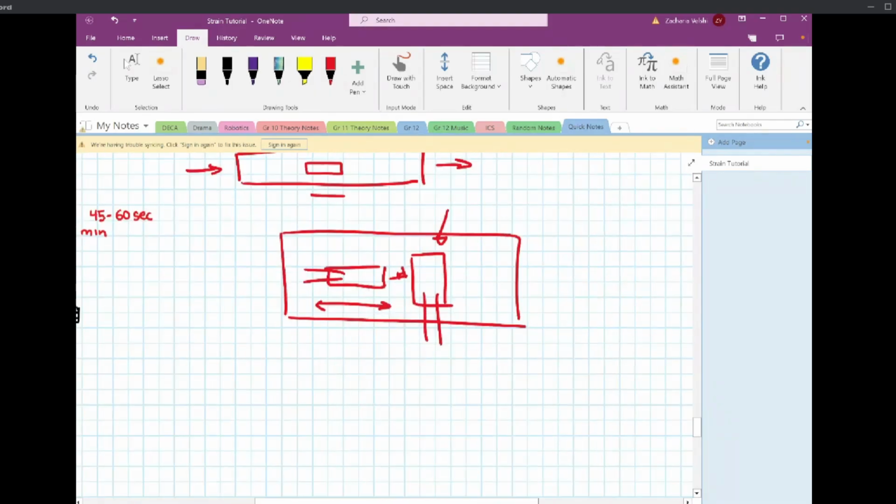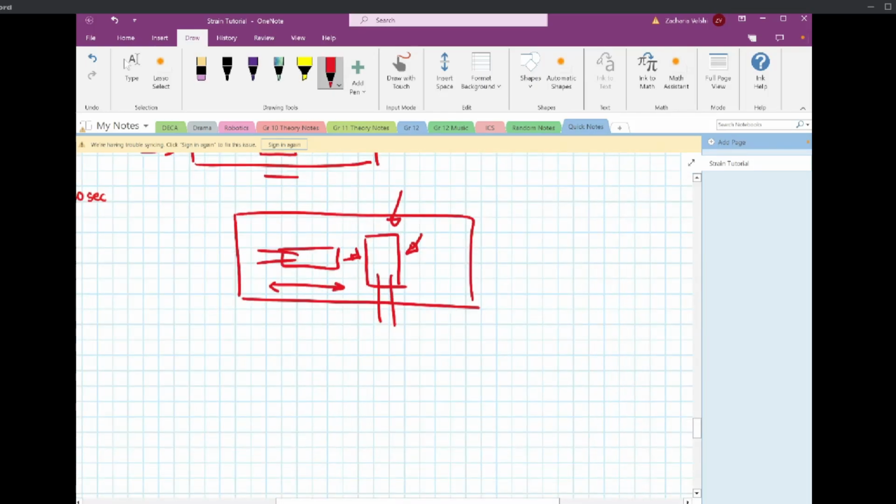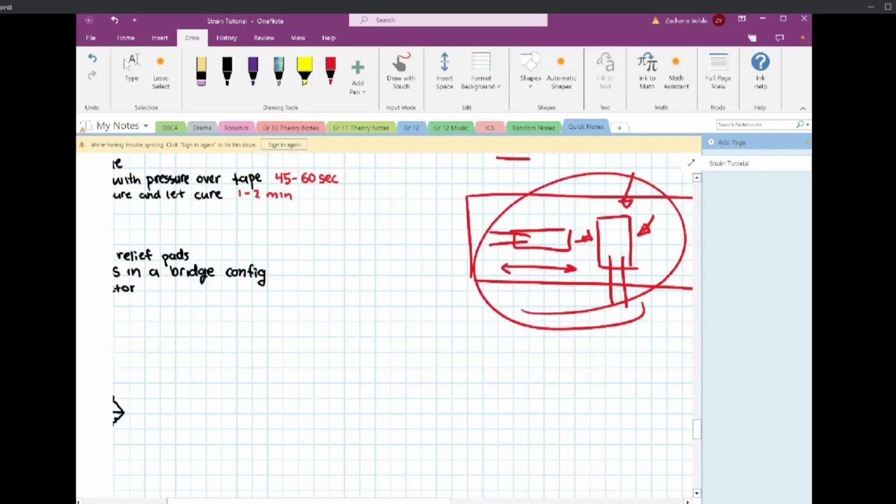What's also mentioned in that video that Ariel posted is these dummy strain gauges that are just used for temperature compensation, not for load compensation, just for temperature, can also be placed on an adjacent member that is not seeing any of the same load at all, but is also being affected by the same temperature. On the BAW, that's not really going to happen anywhere because the chassis is not infinitely rigid. It is a spring. Unless there's some other material that's not directly connected to the suspension, then you can maybe place it on that, but for the most part, this has been pretty reliable for us.